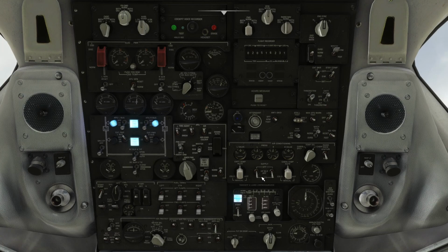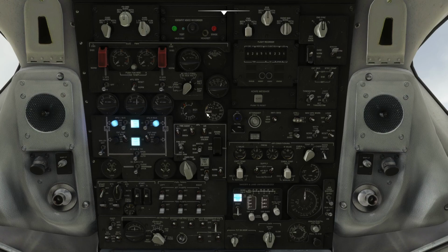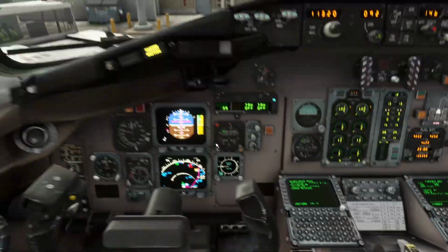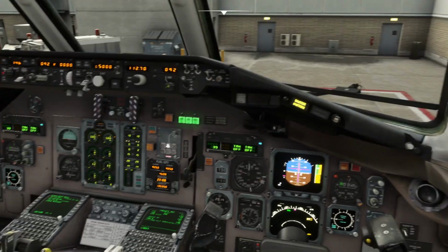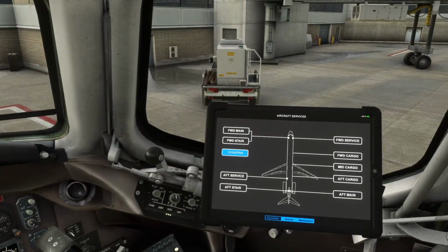In preparation for engine start, these air conditioning supply switches can come off, as well as the bleed air can come on for the APU. That's where it is. So now beacon light comes on, or anti-collision, as it is known.